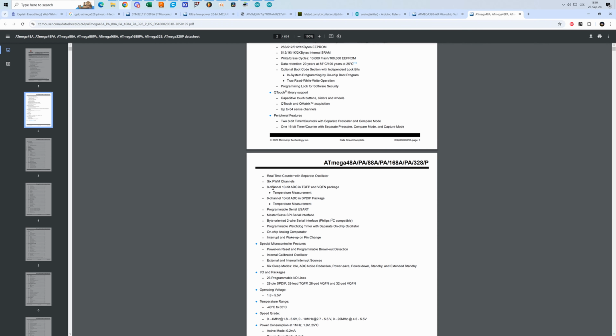You're also going to see very quickly in all the datasheets, if we look at the ADC, what the resolution of the ADC is. You can see here that it is 10-bit. That's going to be one of the first pieces of information you're going to find about the ADCs and DACs. Now, there is a problem with the resolution because the higher the resolution, usually the slower the ADC gets. This also happens with the DAC, of course. So it's always a trade-off between the resolution and the speed.